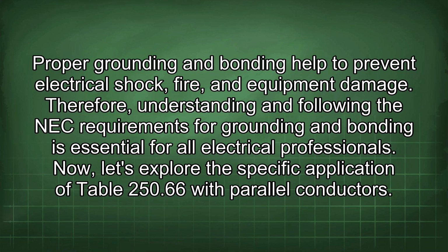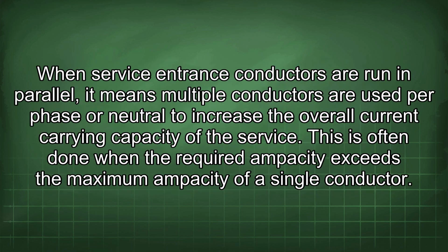Now, let's explore the specific application of table 250.66 with parallel conductors. When service entrance conductors are run in parallel, it means multiple conductors are used per phase or neutral to increase the overall current carrying capacity of the service. This is often done when the required ampacity exceeds the maximum ampacity of a single conductor.